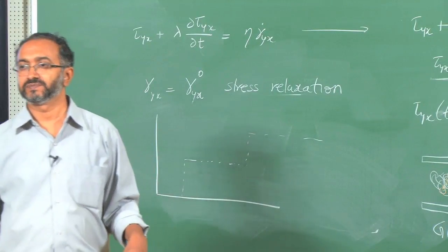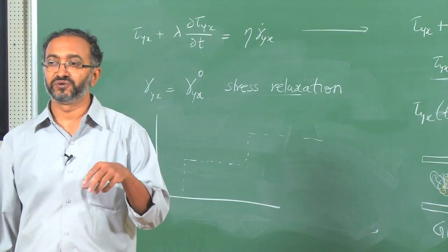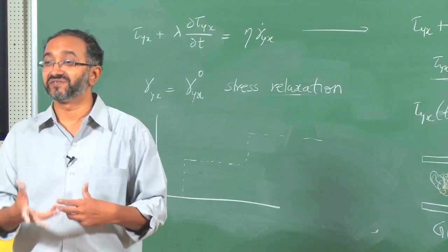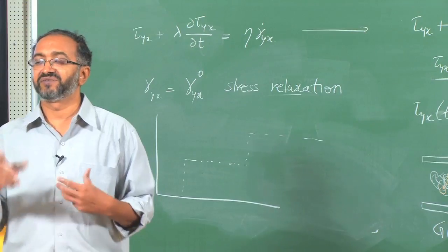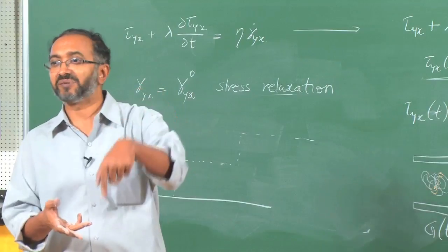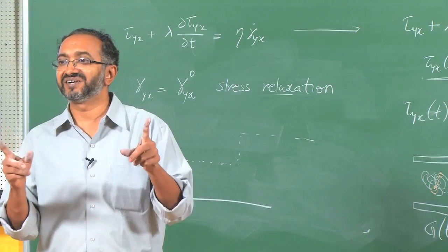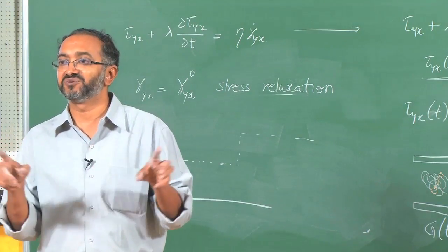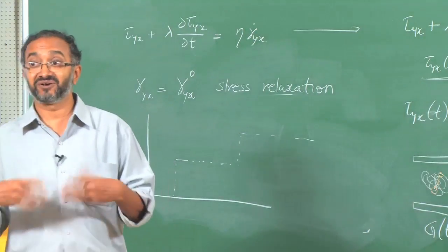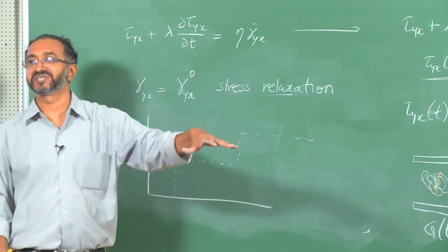I am asking about stress. Stress will remain same. We are applying same stress or? No, if you apply strain, then you measure stress. You cannot control both of them at the same time. When I apply a constant strain on an elastic solid, I cannot again apply some stress. Stress will be determined based on the material. I cannot independently control both of them because both are related to each other through a proportionality constant. Do you follow? Yes. So both of them are not independently controlled. In this case, strain is the one which is controlled and stress is what is being measured.